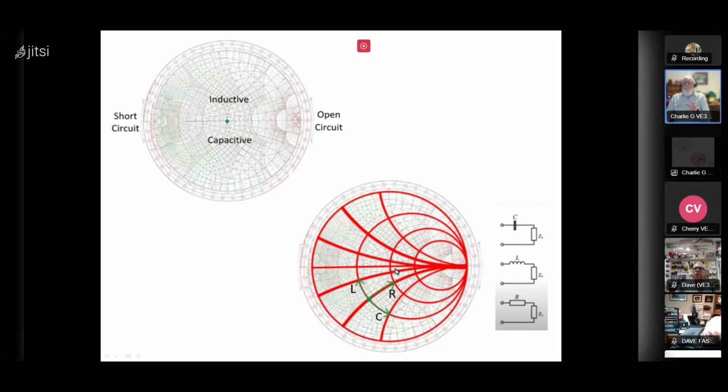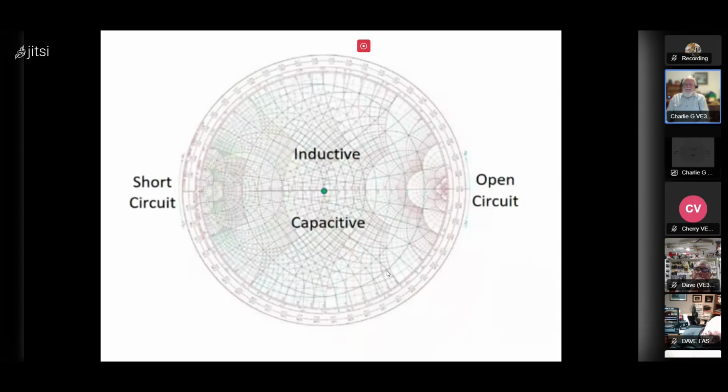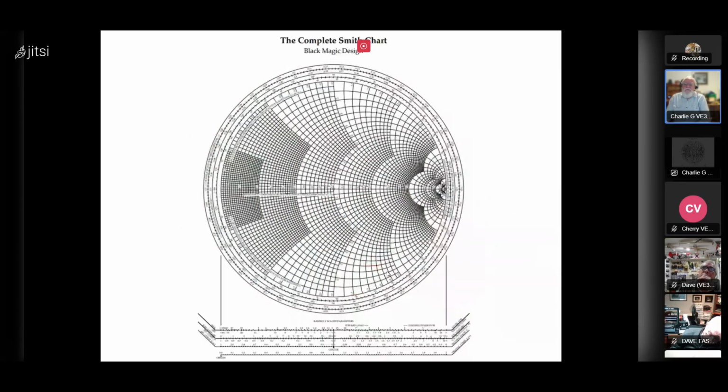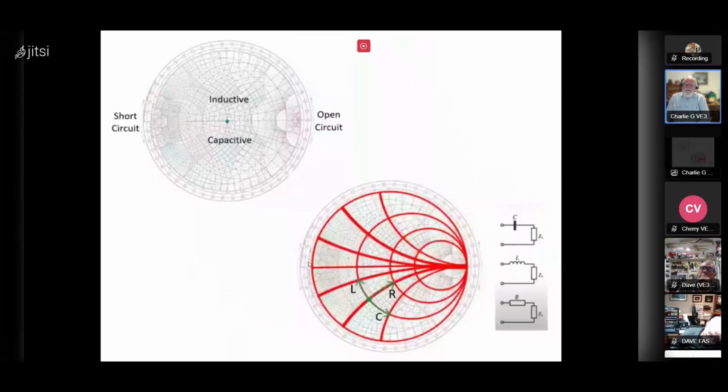it's great to do this on paper. The problem is that the NanoVNA does not give you these two charts. It basically only gives you this one, and with a lot fewer lines on it. So if you're trying to figure out corrections, you may actually need to take the values and drop them on a paper copy of this chart to figure out what you need to put, say, in parallel, for instance, in order to correct the impedance that you're looking for with a single component.